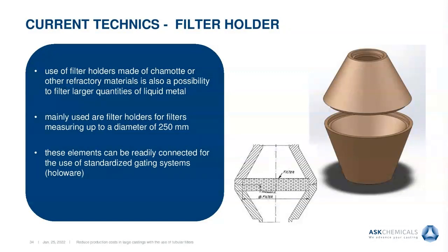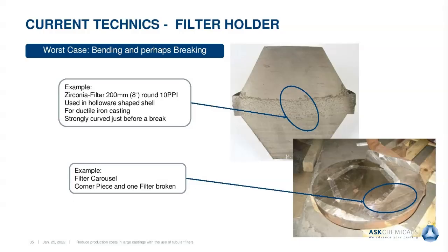But there's also a point you have to bear in mind. It should really be noted that the thickness of the filter must be increased in parallel to the filter size. That means a filter thickness where the required priming of the filter increases so much that not enough heat can be provided by the liquid metal when it contacts the filter. This would at the end lead to an abrupt freezing of the filter, and the filter is then blocked.